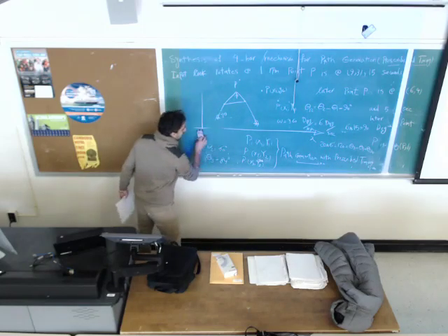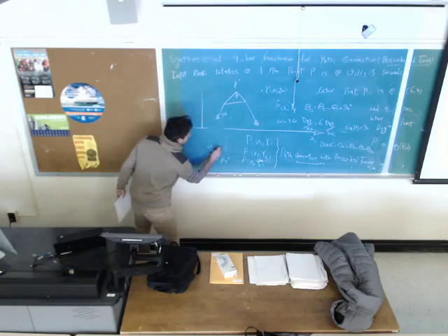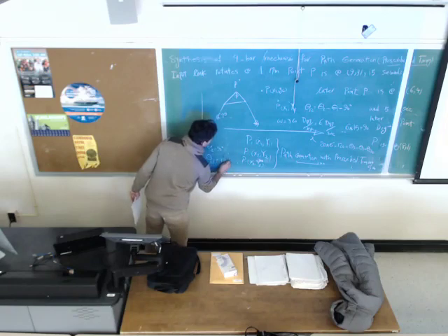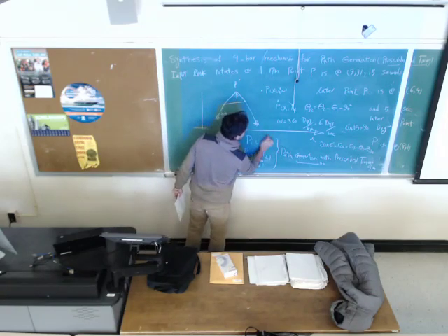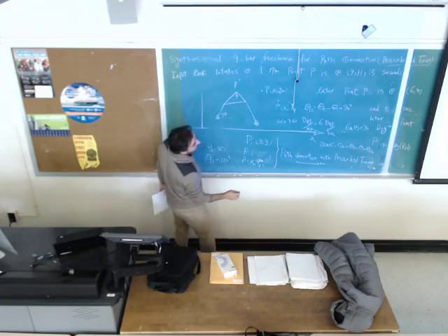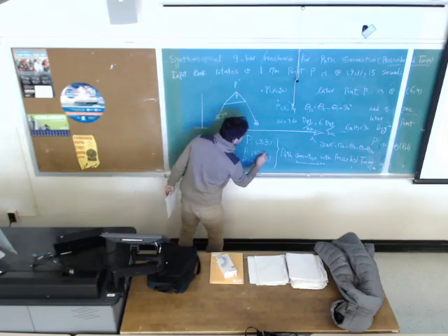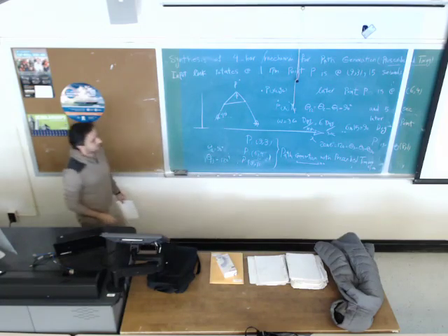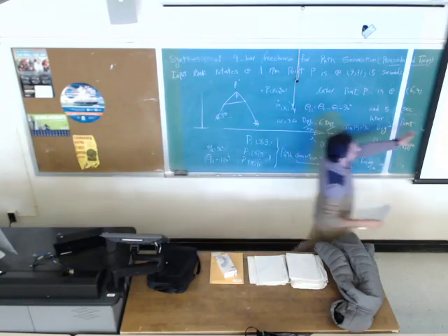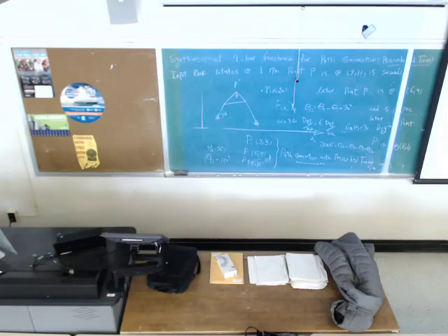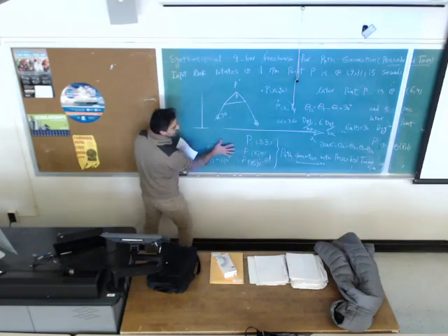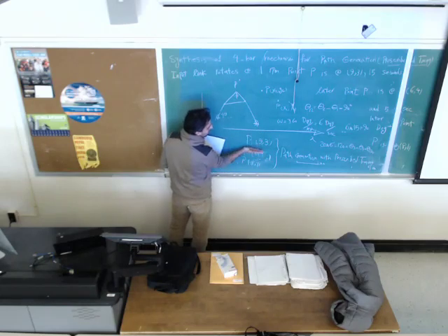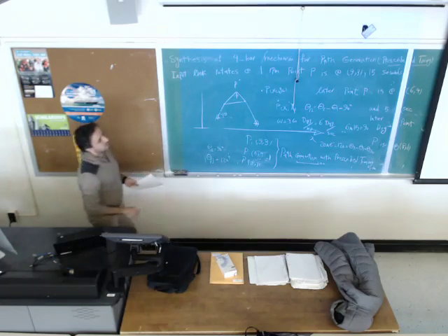So if I want to write it down here, theta 1,2 should be 90 degrees, theta 1,3 should be 120 degrees, when P1 is 9 and 3, P2 is 6 and 4, and P3 is 8, 1. So we would like to design a four-bar mechanism such that it generates this desired path. Good? So if I didn't give you this, and I just wanted to design a four-bar mechanism such that it goes over these 3 points, we just had path generation without prescribed timing.